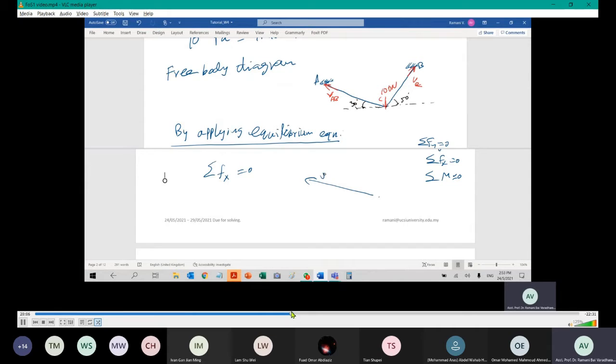Remember these points, okay? This is VAB, and the angle of this one is 30 degrees. Now I need the x component only, right? And this is x and this is y, assuming that the x direction is in this way. Initially we assume the x direction to be this way. Then we will decide whether it is the correct answer or not, right? And y downward, because the load is acting downward, so I can assume the vertical component to be upward.